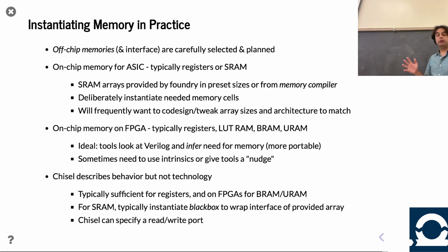But at some point, maybe it's going to run out of URAMs, or at some point, the URAMs that are available are so far away from the rest of your design, you actually wish you would do part of that not on URAM, but actually using registers or LUTRAM to be closer and keep it more dense. If you tell the tools, hey, you must use URAM, that's the optimization parameter you're taking away from the tools. So actually, you'd rather have the opportunity.